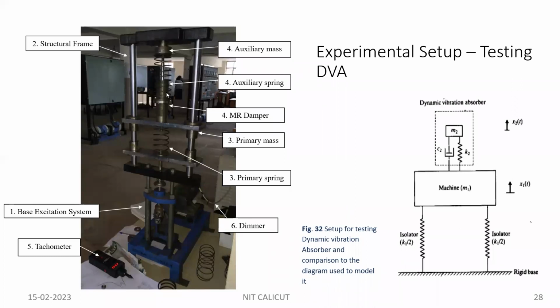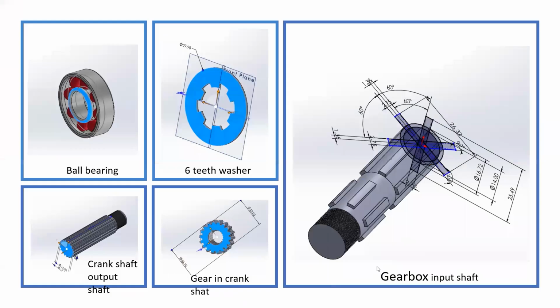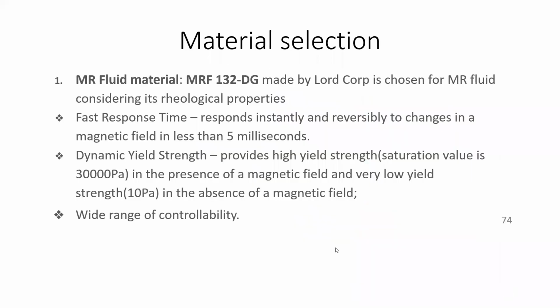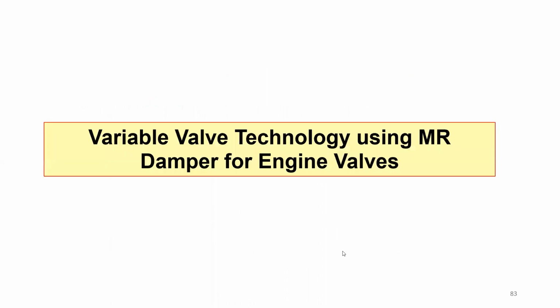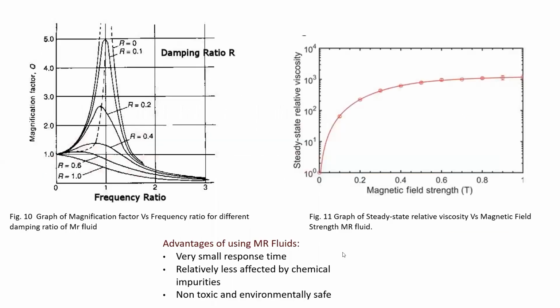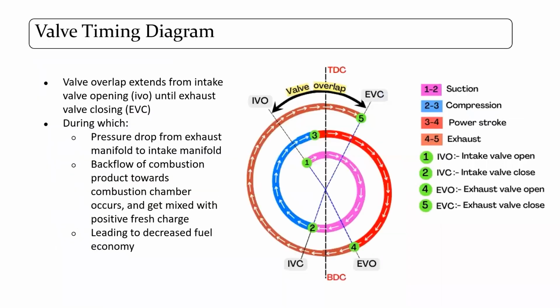And if you have more instability, and you are able to control that instability or vibration with the MR damper, then it is good. That setup is the same; principle-wise, it is the same. Here I am giving the motor and moving up and down. They have used a hydraulic cylinder to move up and down because that is available to them. That is for high power. We have demonstrated for low power because we are using only a few kilowatt motor. They are using big hydraulic power. That's all the difference, but concept-wise, everything is the same.